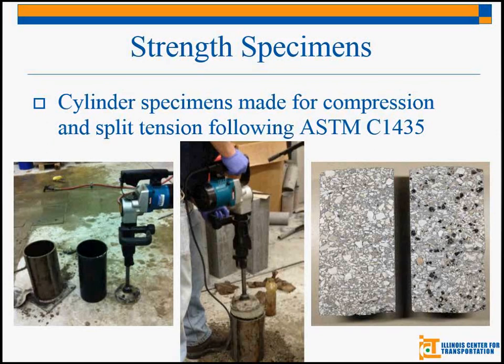And so we use this vibratory hammer following ASTM C1435. And as you can see with the specimens here, when they're split in half, you can see that the aggregate is really, really close together, which doesn't quite look like a typical PCC mix. It's, like I said, a little more dense.